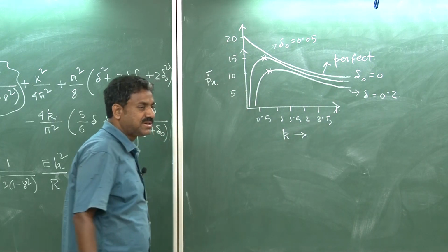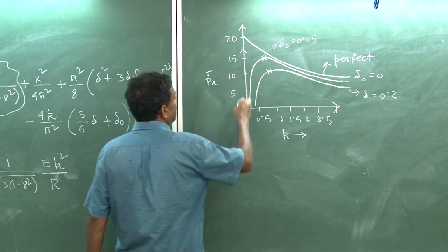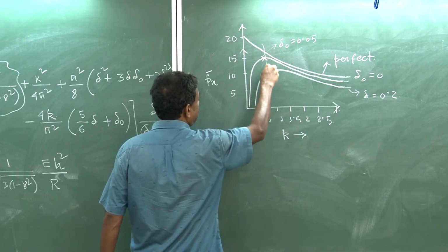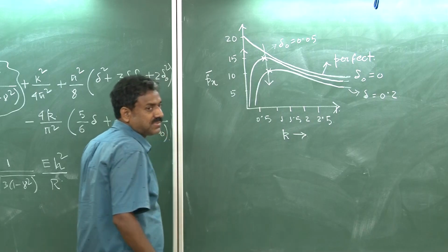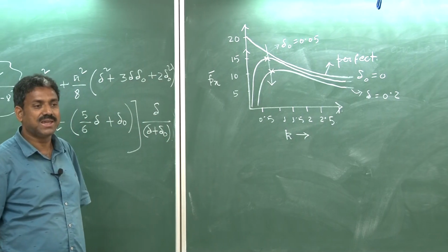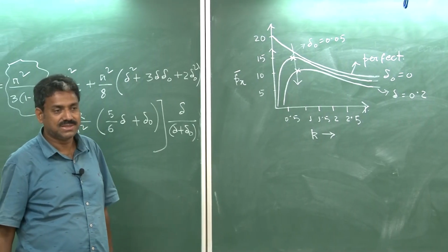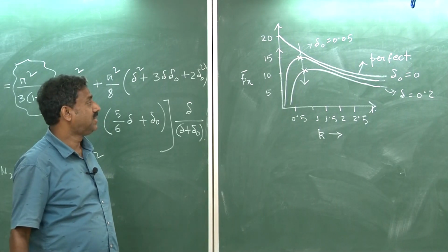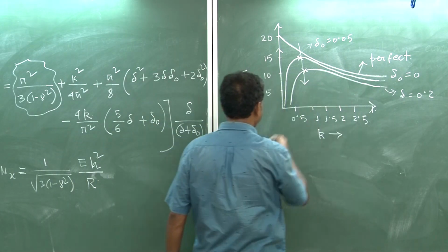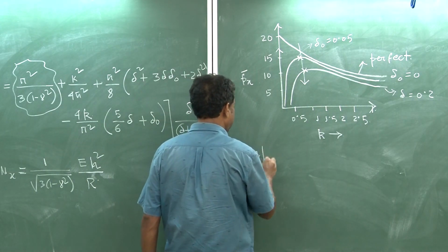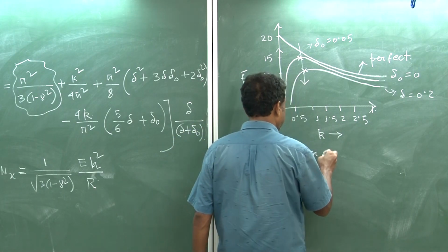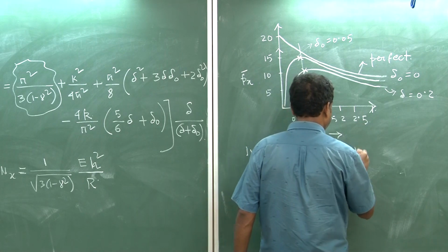But what is most interesting to see here is that there is a decay. You see that there is huge decay in the critical load. And why this significant decrease in the critical load is because of imperfections. You see that? So, this really shows the imperfection sensitivity, okay.